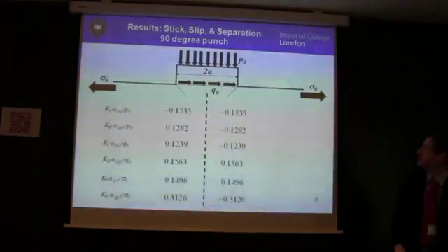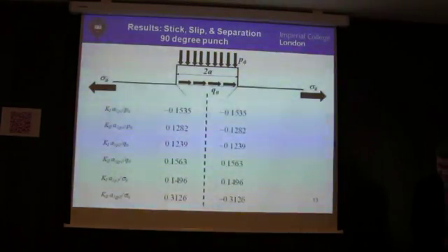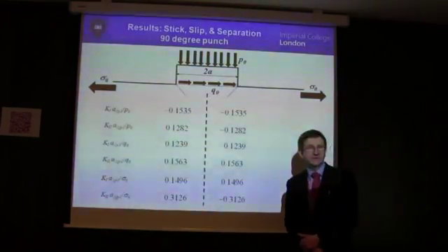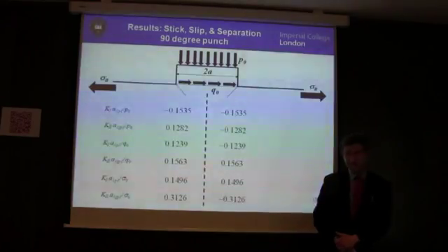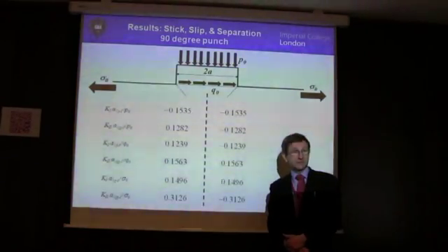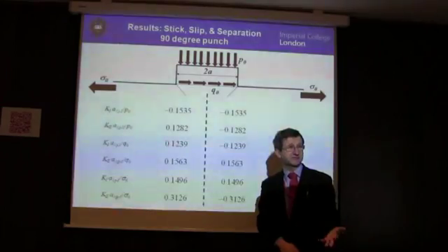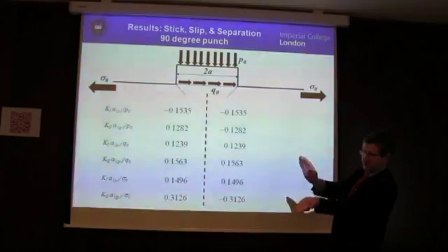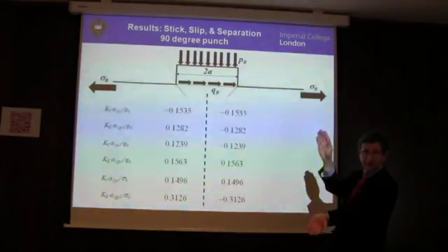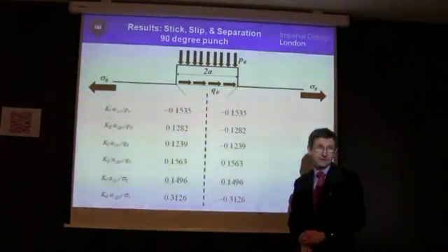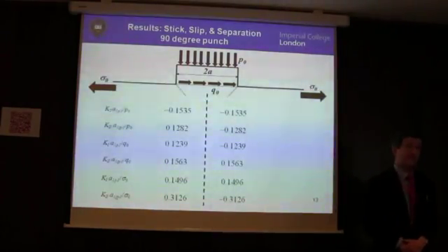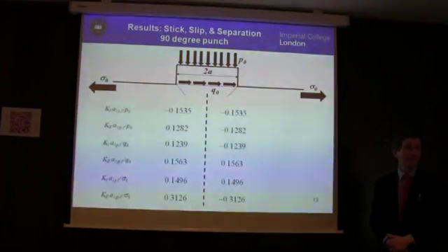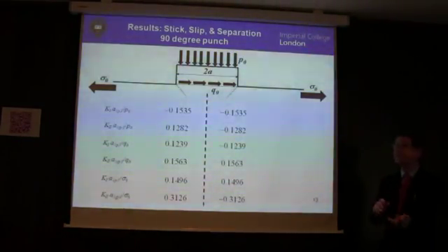Now, I want to make this point next. When you do notch calculations, you can afford to be very careless about the sign of the stress intensity, because the plastic zone is positive definite. It only depends on the square of the stress intensity factors. So whether you're crushing a notch closed in mode 1 or pulling it in mode 1, you get the same implied solution. Of course, you've got to be much more careful than that when you've got a contact present, because the contact will separate. It cannot support any tension.